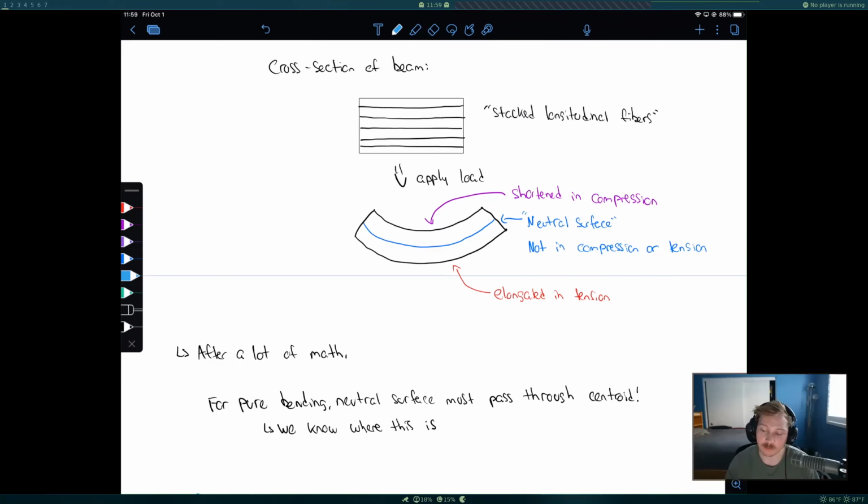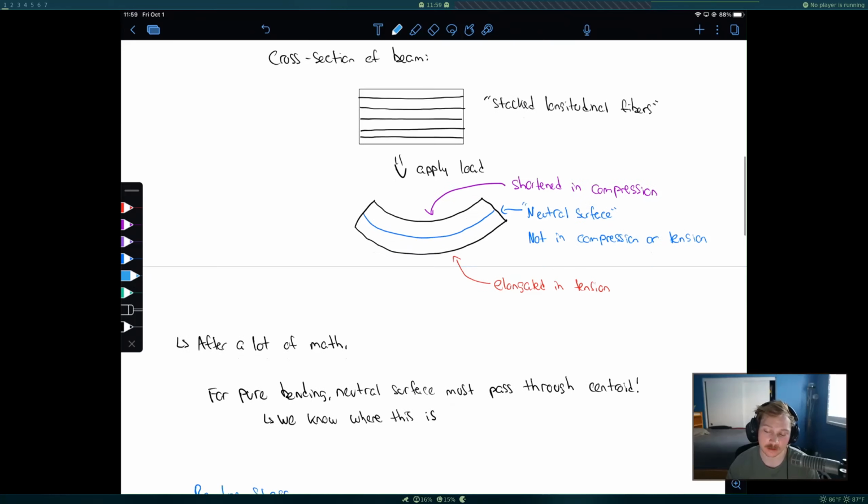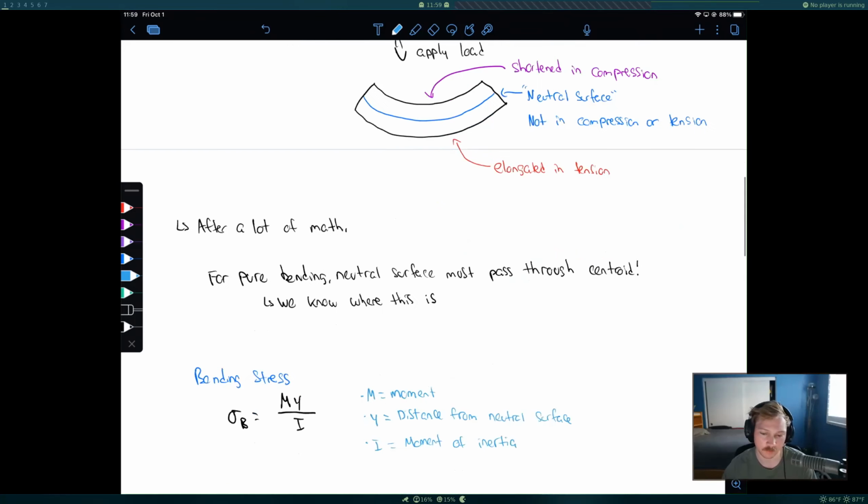So in the lab, remember that we have the strain gauge on the bottom, and not the top, but to repeat myself again, in theory, both the top and the bottom are going to have the same stress, and that's where the maximum bending stress is going to occur for the beam.